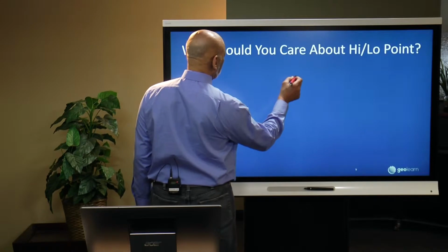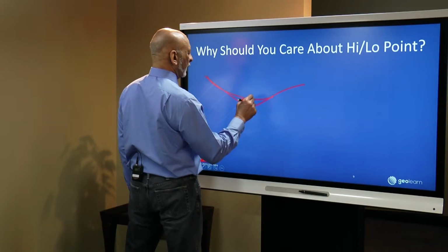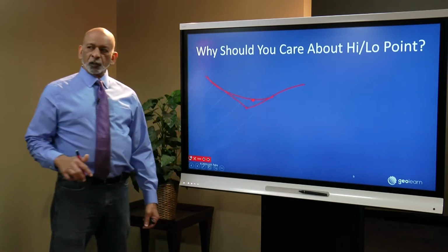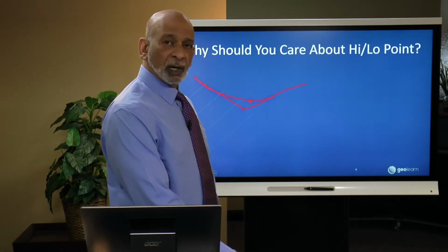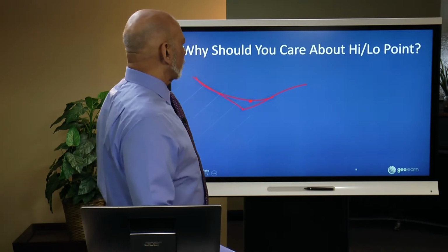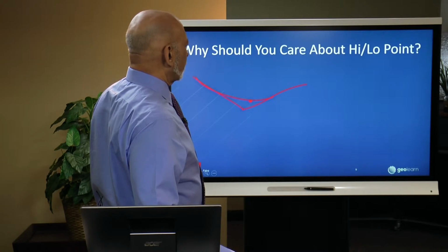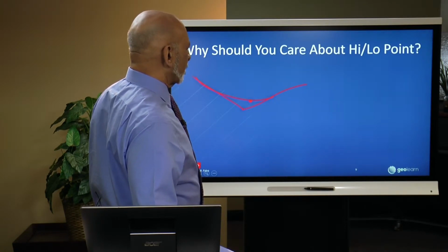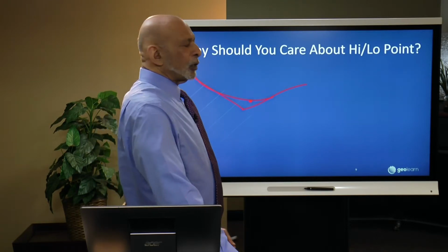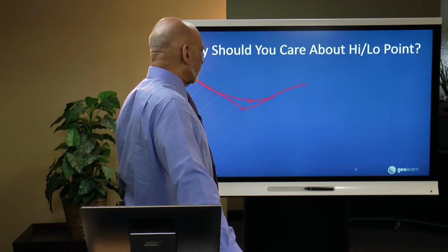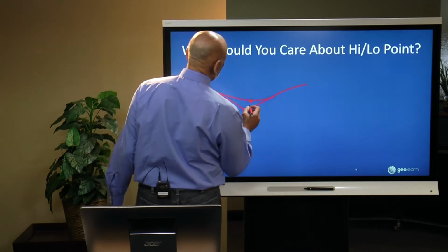When you have a low point situation, you need to know where the low point is, because very often your storm drains will come together there to pass water under the road perhaps. So it's a very critical thing to know where the surface of the curb is going to be, or the surface of the road is going to be, to make sure that you know where to put the storm drainage collection system. And if you have a pipe that goes through the road,